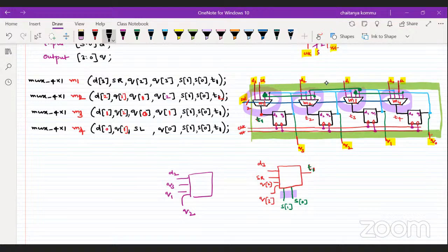Okay. It's very, very important when you are doing structural modeling that we identify where the signals are coming from properly. We have to set them. Otherwise, there is a problem of erroneous output. When you are writing the program and doing some logic, even if we follow the same port mapping, the circuit connection is correct, but you cannot get the expected output, because instead of one signal going to one line, it may not go to that line.